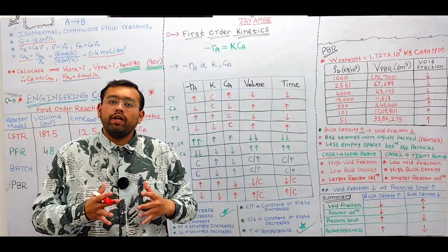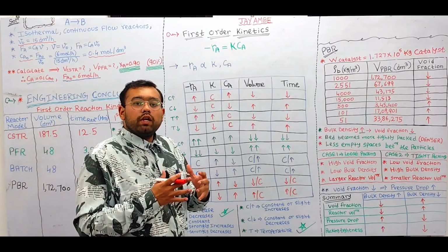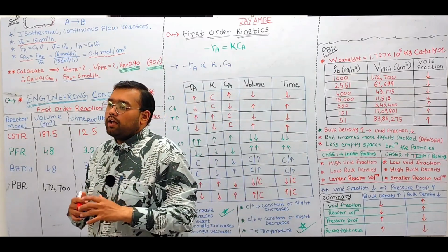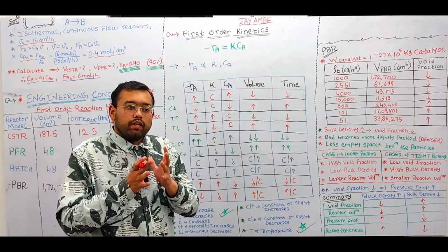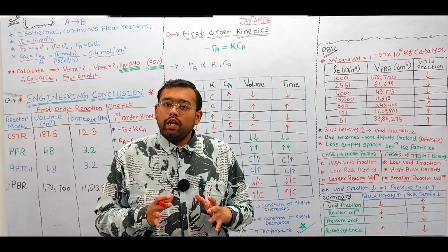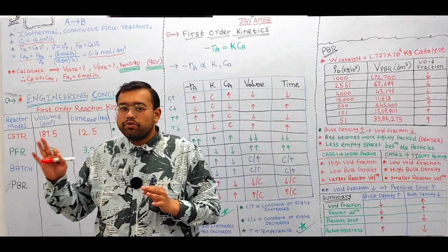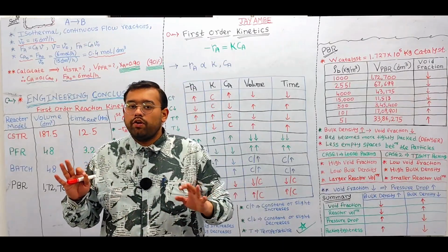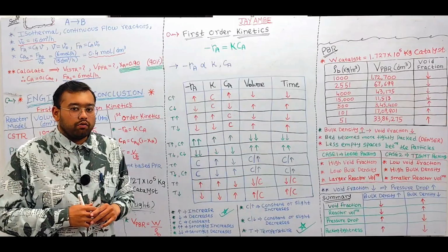We feed all the feed mixture to the reaction environment of the batch reactor in a single go, and finally, after feeding all the feed mixture, we close the inlet stream. So now there will be no inlet stream and no outlet stream. The inlet stream and outlet stream remain closed during the run of the reaction.